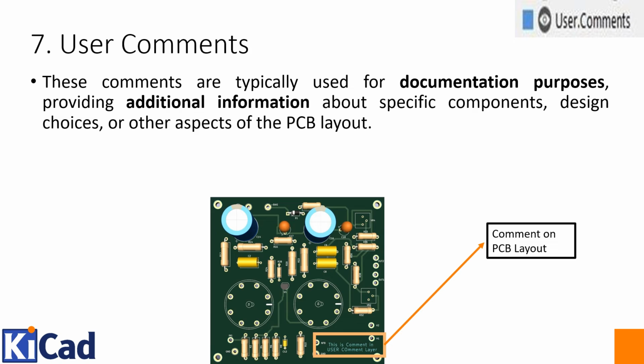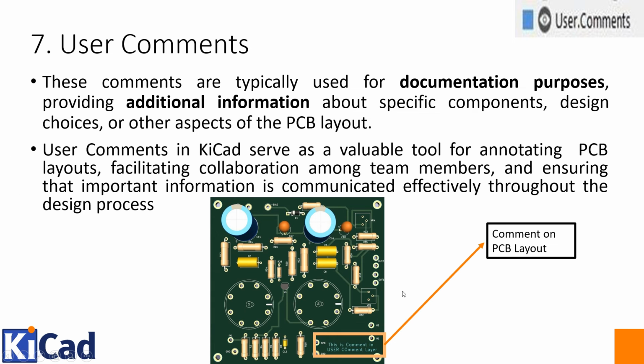These comments are typically used for documentation purposes, providing additional information about specific components, design choices, or other aspects of the PCB layout. Over here you can see that in the previous slide we added a comment in the PCB editor, and now in the 3D view you can see that this comment is added over here on this 3D view of the PCB. User comments in KiCad serve as a valuable tool for annotating the PCB layout, facilitating collaboration among team members, and ensuring that important information is communicated effectively throughout the design process.